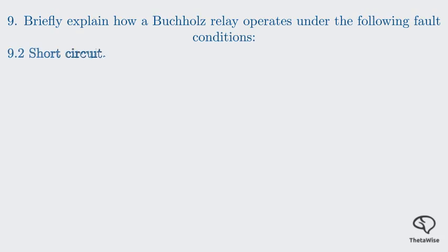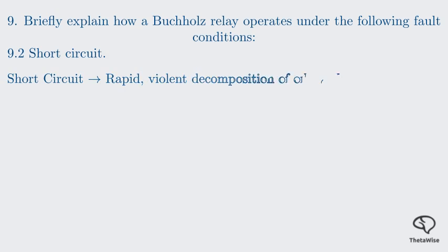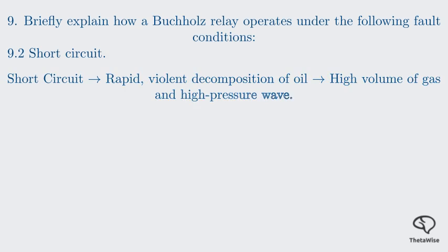This is a much more severe fault. A short circuit creates a massive sudden surge of current, leading to a rapid and violent decomposition of the insulating oil. This rapid decomposition generates a huge volume of gas almost instantly. The oil volume expands very quickly, creating a high-pressure wave.